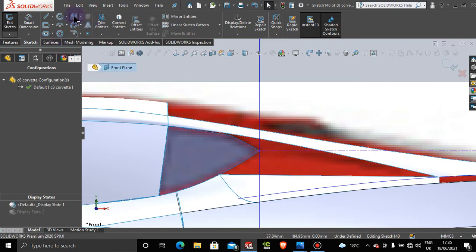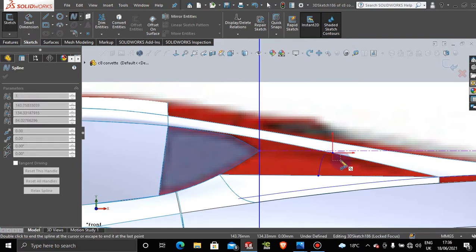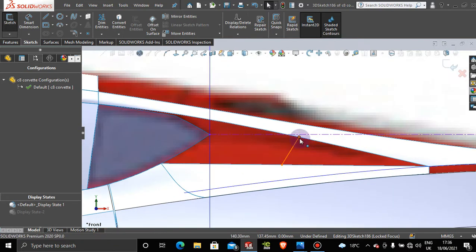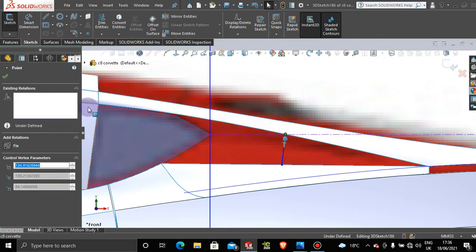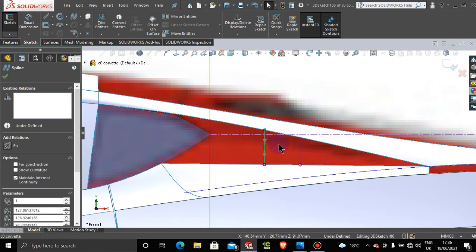Let's add a curvature here. Of course, we want a 3D curvature. So sketch, 3D curvature, 3D spline. I'm going to go from this edge to this edge. And it's going to be a straight line. We don't want any coincident relationship in that area there. So pull that straight. And then we can adjust here kind of where we want it. Okay, so that's touching that side, which is good. And this touching this side as well is good. And now that moves perfectly. So it's somewhere halfway throughout, somewhere about here.